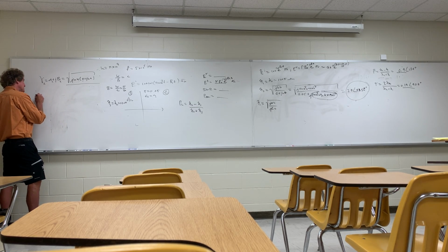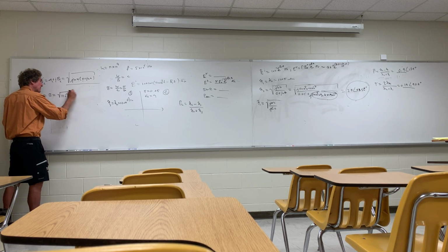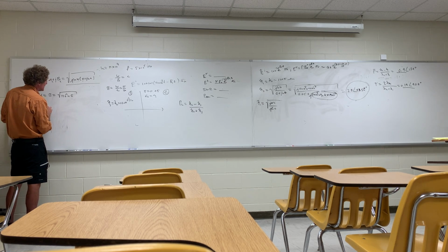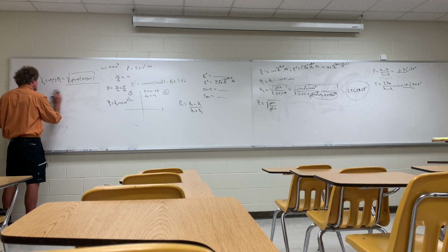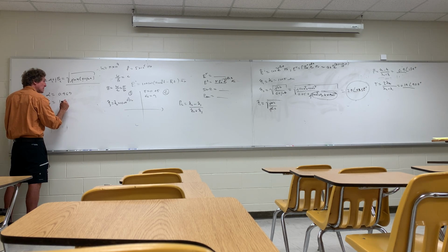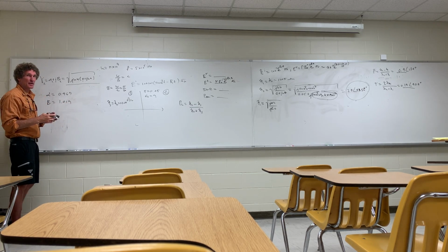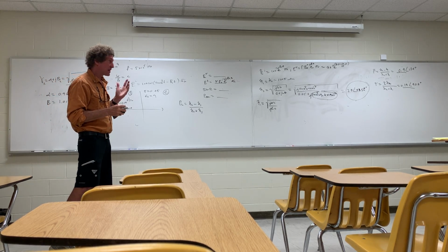I pretty much can tell you, you're gonna get alpha equal to beta equal to the square root of pi f mu sigma, about. They're not exactly equal to each other in the solution, but they're gonna be very close. All right, what do you get? What do you get for alpha? Alpha is 0.969, and what's beta? 1.019. Real close. They're different, but very close. Y'all follow me on this? And I know that it's gonna be about that.